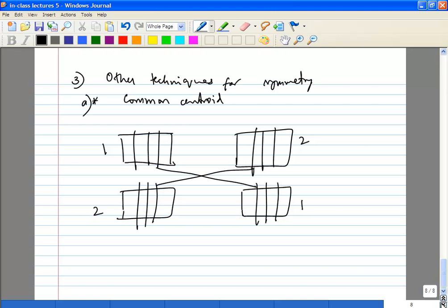So let's call this A. Obviously other very basic things. Orientation. Obviously, if you want to match 2 transistors, let's say one was like this, you're not going to make the other like this, that's for sure. That's very stupid, right? So you're definitely going to make sure they have the same orientation, right?